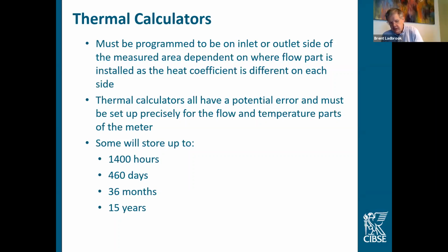Oh, they do, and that's a very good question. Say, for example, the flow sensor is on the supply side to the hospital wing, that's what we're metering. Then it is constantly looking at the temperature probe, and in the ones that I'm familiar with, that would be T1, temperature probe 1, looking at the temperature at that flow sensor and constantly updating the K factor based on the temperature at that exact time.